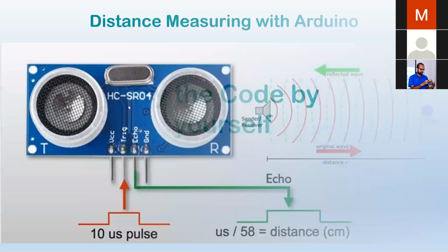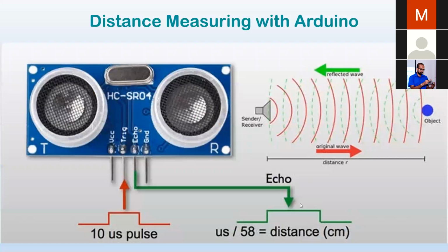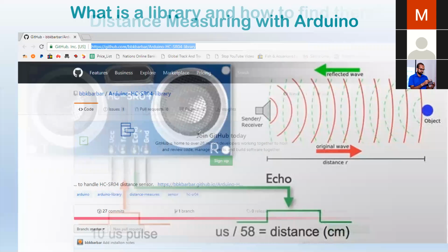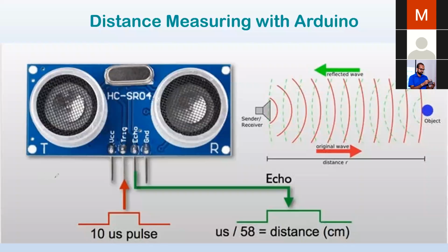This is how you measure the distance with this sensor. This is the HC-SR04 sensor, the ultrasonic sensor. I will tell you how this sensor works. You have to use a library anyway. When you trigger this pin, you send a really small pulse to this pin, and it is going to emit 8 pulses from this thing. We call this a transmitter. Those pulses go and hit some obstacle and come back to this pin, this receiver. We call these transducers.